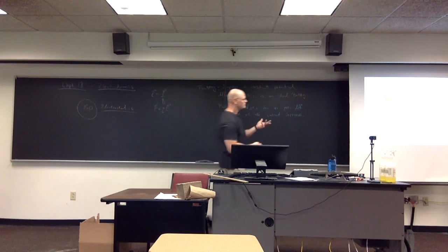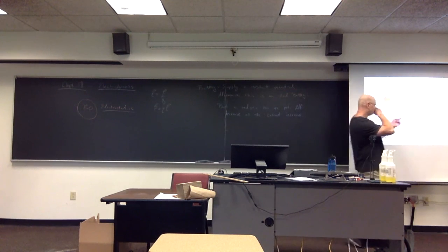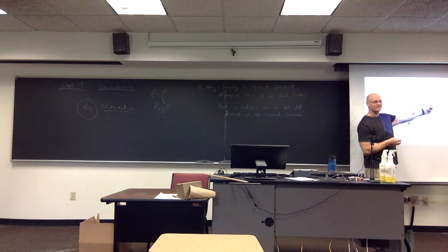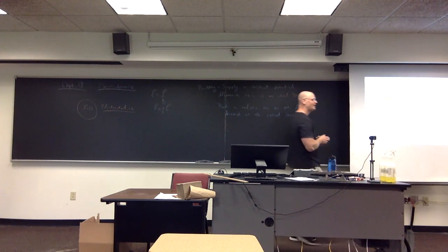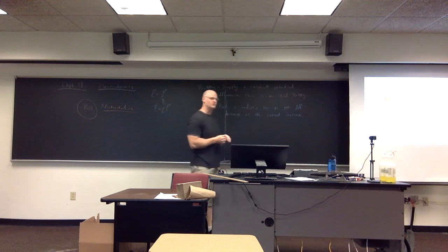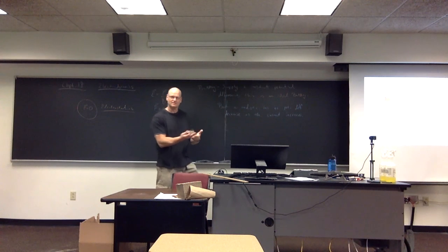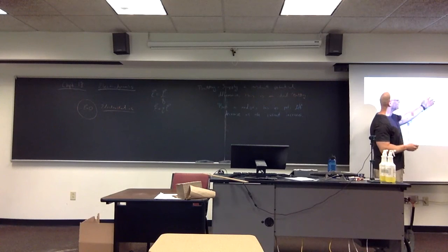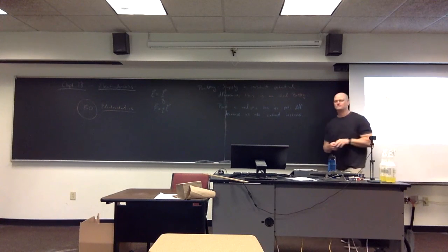So my electrolytic fluid now becomes positively charged. It doesn't want to stay positively charged. So what happens in that case is from the cathode, I start depleting negative charges from the cathode into the electrolytic fluid, trying to get it to neutralize, so it becomes zero charge. So my negative charges start coming off of the cathode, leaving my cathode positively charged.